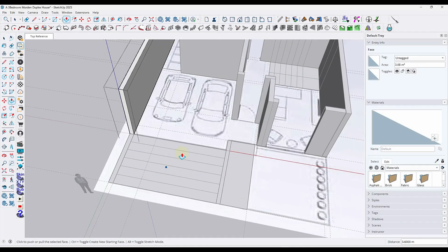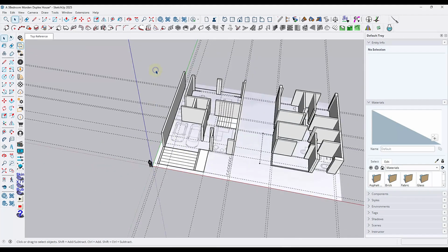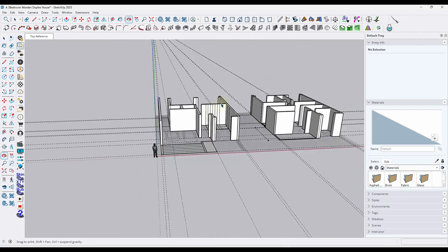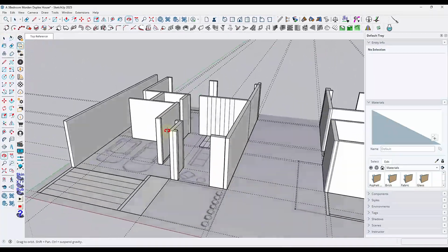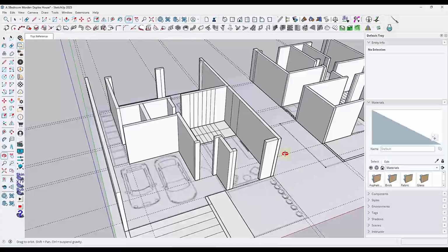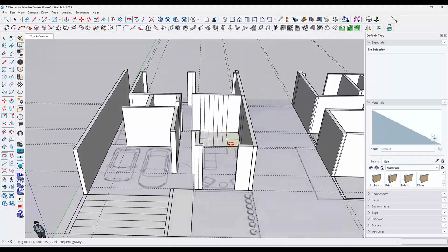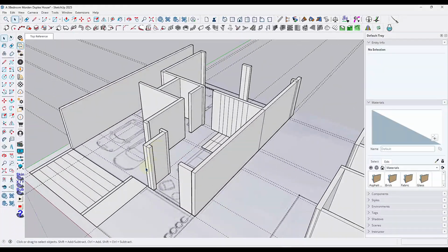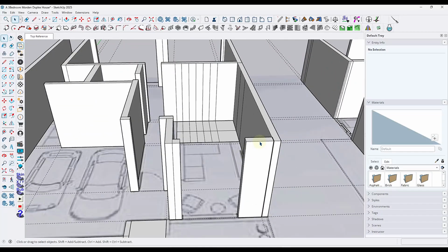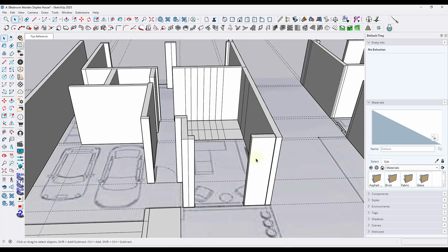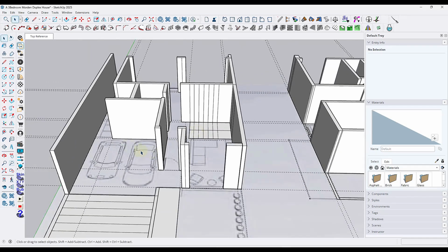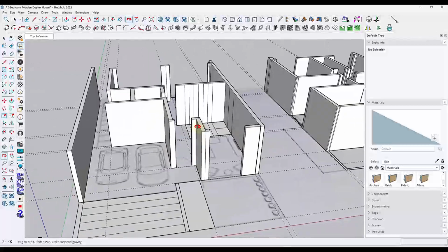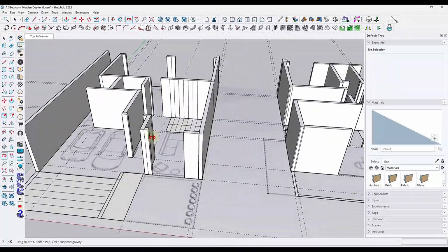After doing that, you can click outside or press Escape to go out of the selection. Okay, which is a very good time to make a window or a door closure. Currently, I'm going to use 400 down, so we can have a lintel level for our windows and doors. Although we're not going to use that randomly for all aspects, for now, we're just going to use that.